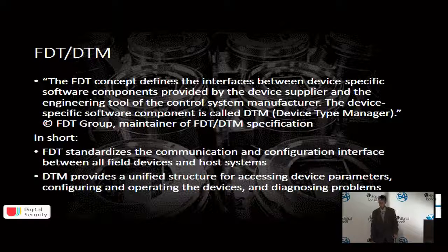According to the maintainer of the FDT DTM specification, the FDT Group, the FDT concept defines the interface between device-specific software components provided by the device supplier, the device vendor, and the engineering tool of the control system manufacturer. The device-specific software component is called DTM, Device Type Manager.